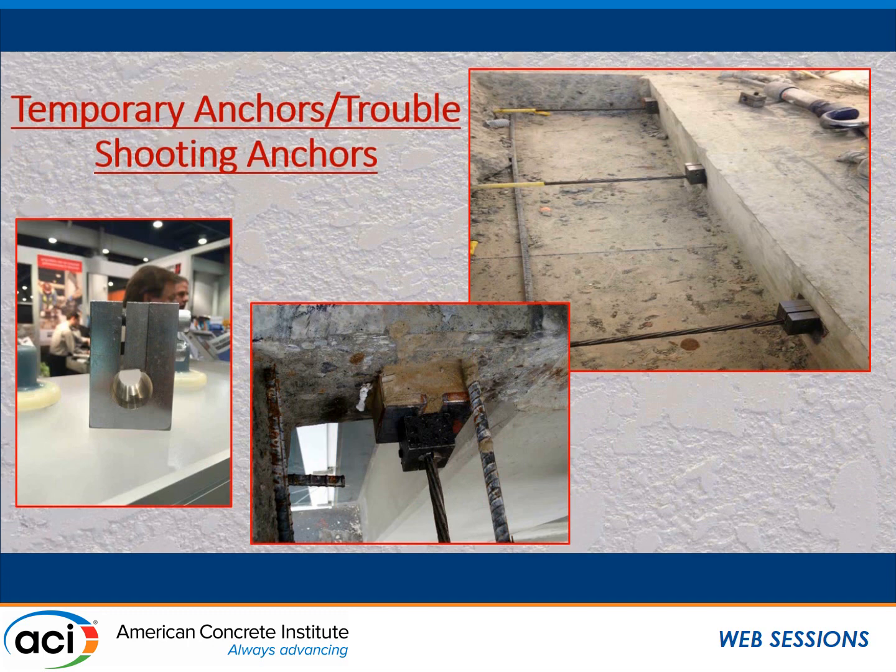So the use of rescue anchors, maybe there's somebody in the room, maybe there's somebody out there who knows it, and boy, I'd love to find out about it, but we only have the ability of capturing one cable at a time. So if you have groups of 2, 3, 5, whatever it is, there's no way of grabbing all those at one time and de-stressing. So typically a temperature tendon is what we can capture, and you put in a temporary anchor. You can then create your new opening, a new anchorage, and re-stress. They're essentially a disposable item that you use. They work very much like a permanent anchor, but they are not considered to be permanent by code.